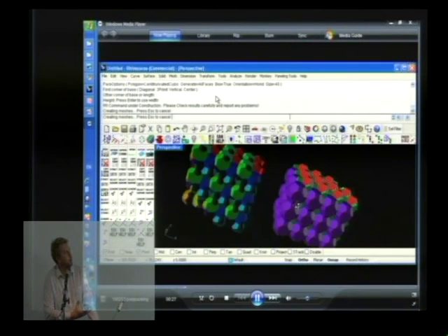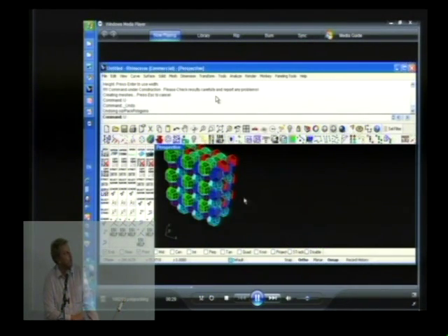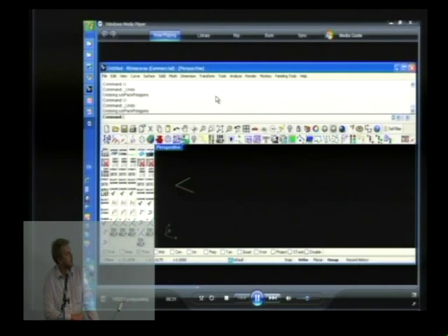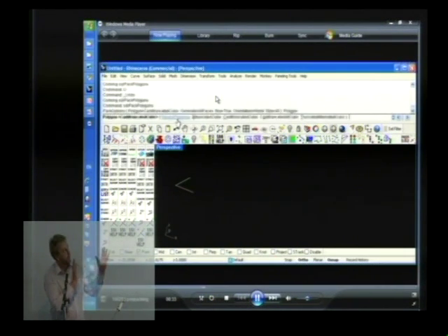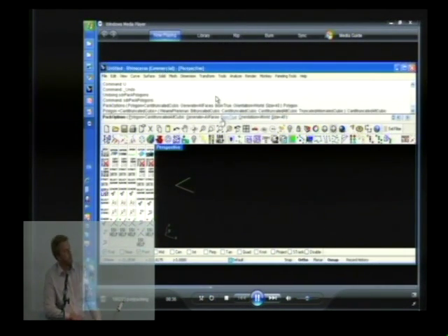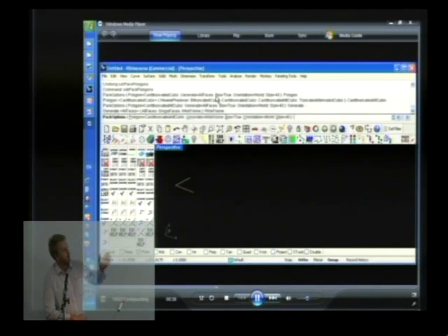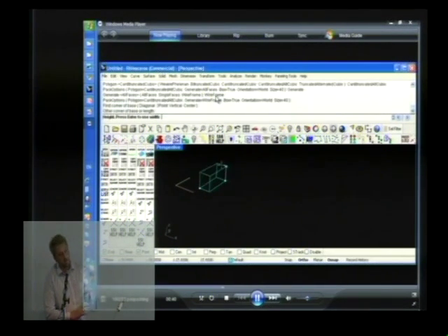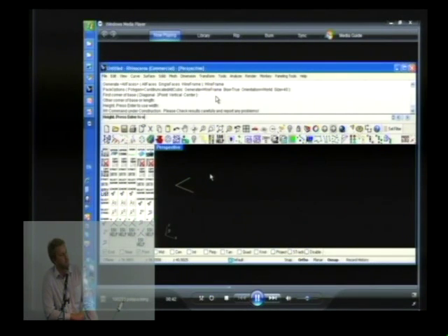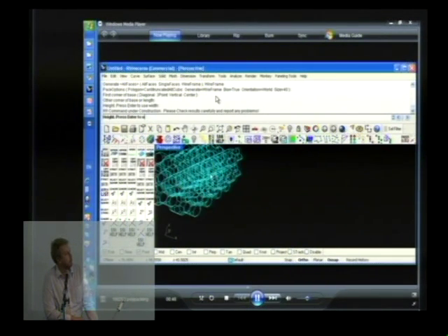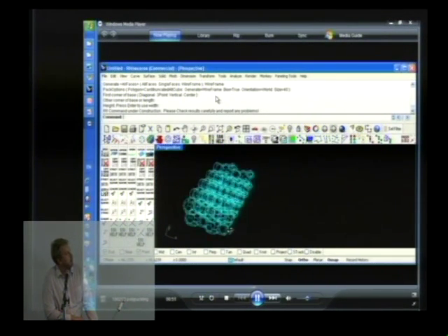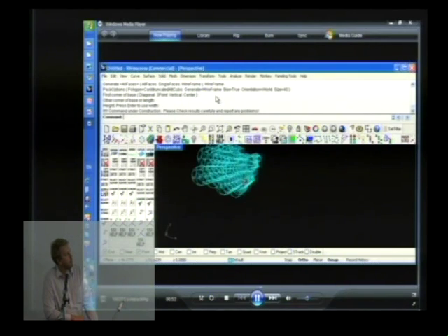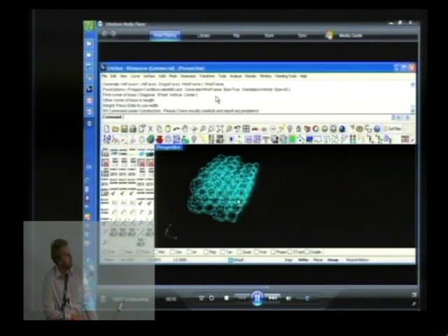So the Beijing Water Cube was quite a stunning example of a novel piece of architecture where they effectively did that molecular cell packing of a volume, and then they actually rotated it around 2 axes and then intersected it with the rectangle that formed the facade of the Water Cube, and that gives that soap cell water type appearance that was prominent and I thought looked quite nice in the facade. So parametrically now that sort of operation is available in Grasshopper via the plugin.